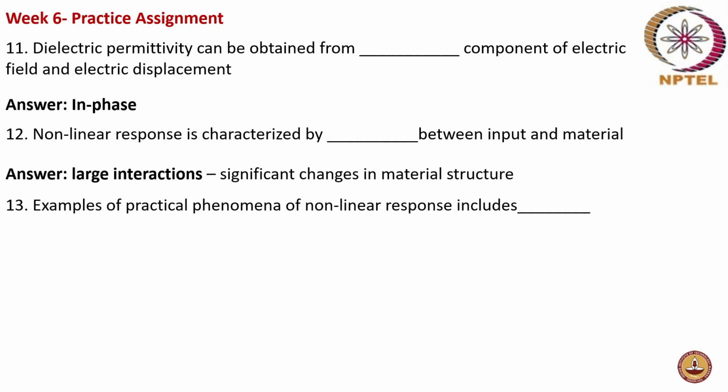Rheological properties, we can say. Is it rheological properties? Again, in rheological properties, you will have linear response and pseudoplasticity. Yeah, somewhere you are saying, but not exactly. It is actually, as you said, plasticity. That means plasticity means there is yielding. So yield is an example where the response becomes non-linear because there is a significant microstructural change or there is a permanent deformation.